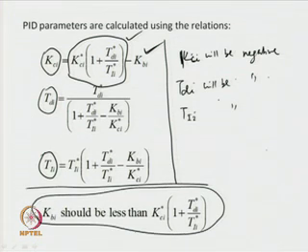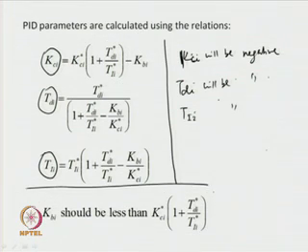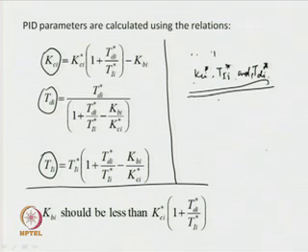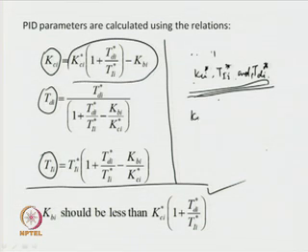So, design of Kbi depends on the values of Tdi star, Tii star and Kci star. Although we might have got design values for Kci star, Tii star and Tdi star, those might not be acceptable to us unless this condition is satisfied, unless this relation holds, unless Kci, Tdi and Tii are positive.